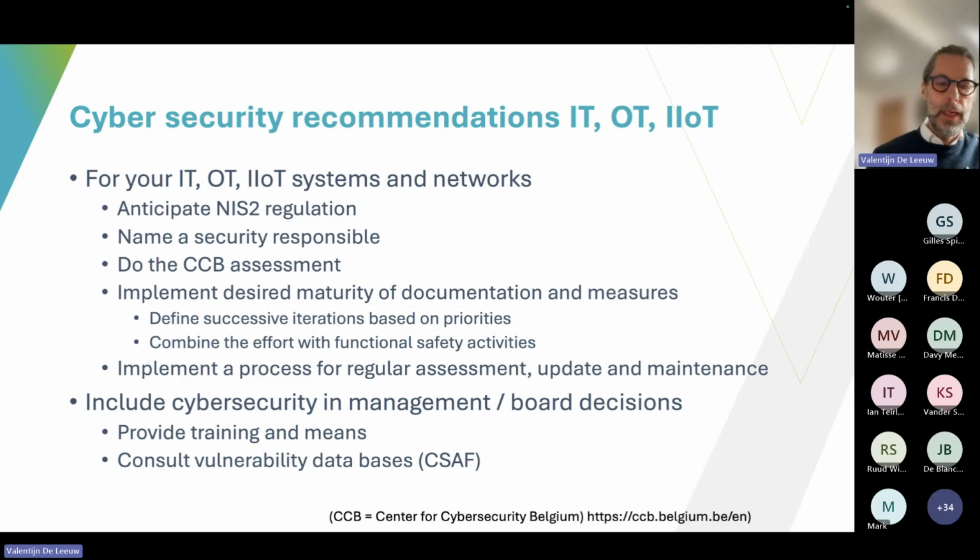You decide where the weak spots are and what you need to improve, and you do that in successive iterations based on your priorities. And my recommendation would be to combine that with functional safety activities, because you need to analyze your equipment anyway. You can just add the cybersecurity to that analysis. And then when you reach the target levels, you can implement a process for regular assessment and updates.